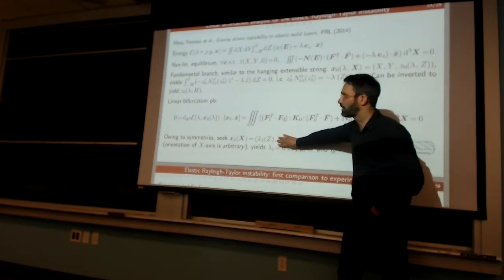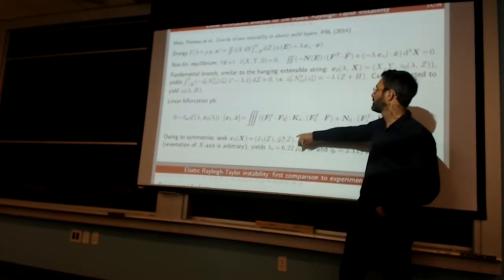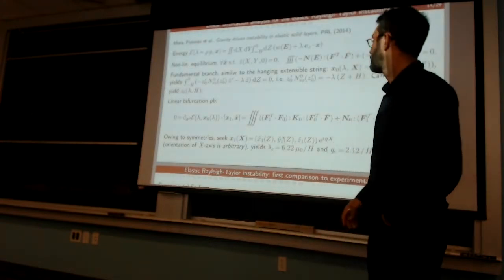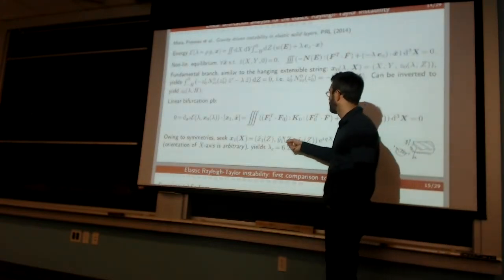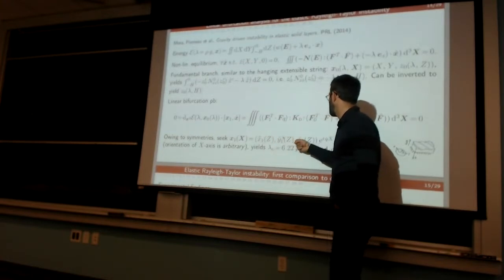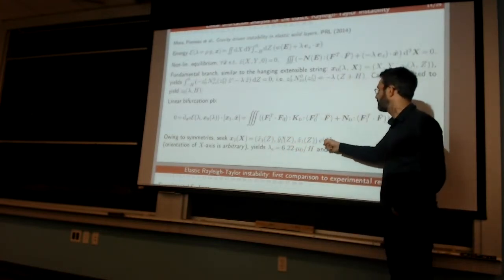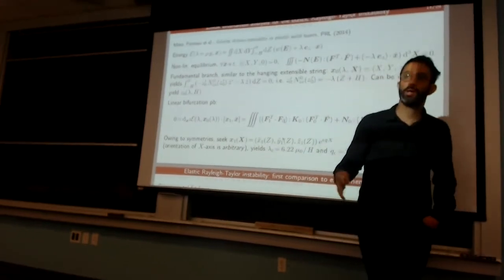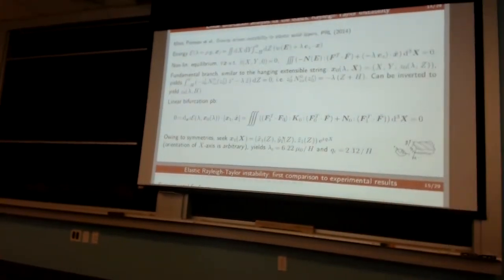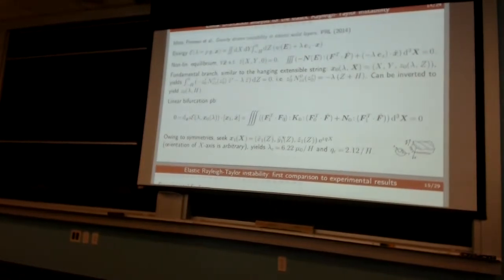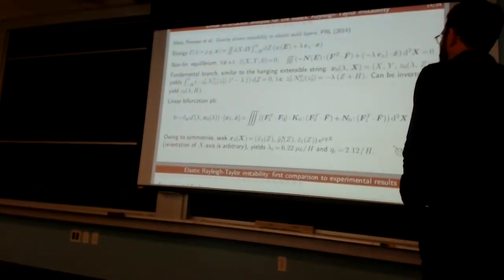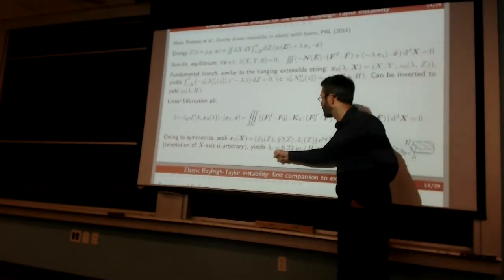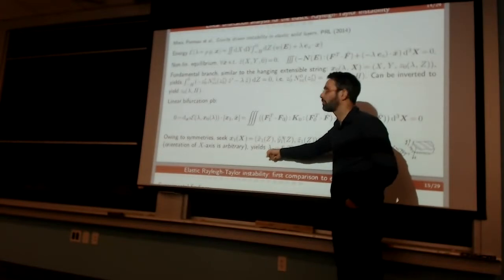So we just need to plug this special form into this problem and solve for the tilde quantities. And then we come up with, it's actually doable analytically, and there's a solution that gives you these expressions as well as the value of Q, as well as the value of the load. Okay, so it works exactly like before. The starting equations are a little bit more complex, but the method is exactly the same. And if you do that, you select the value of the load. So that's, you remember, that's rho g.